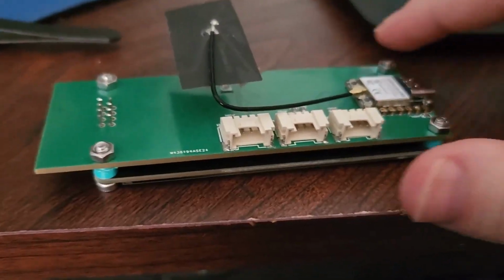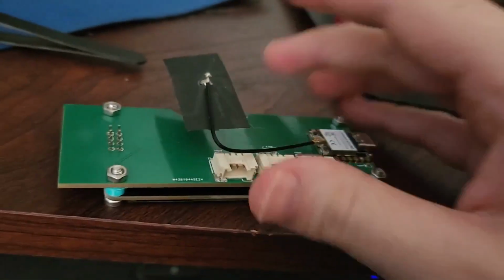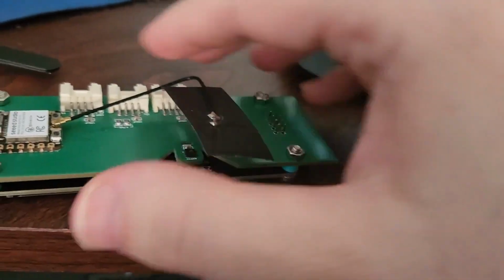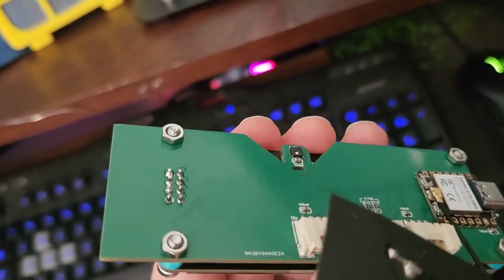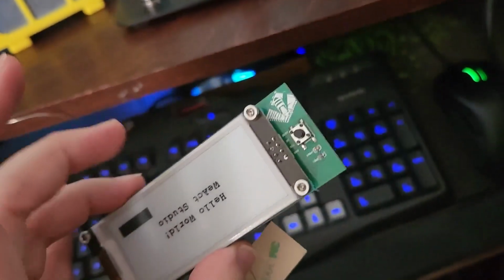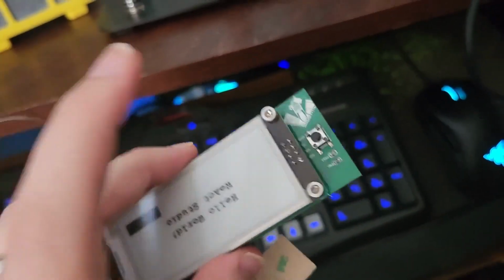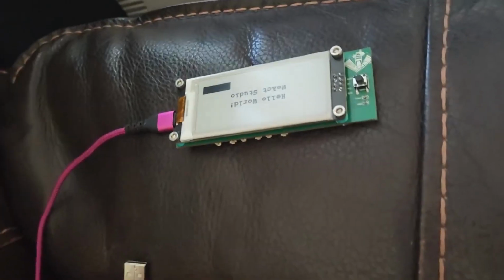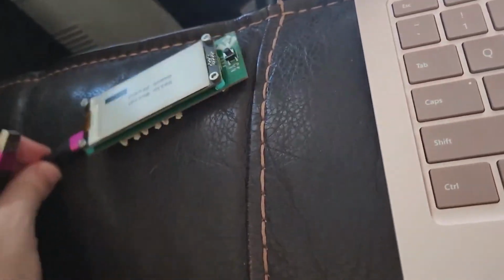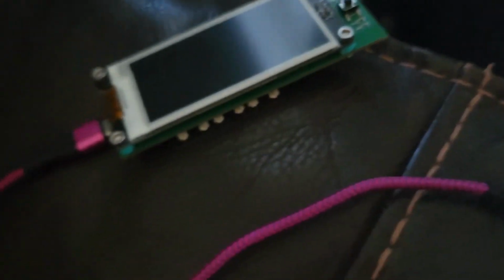I attach these temporary nuts for the standoffs here, just to keep it in place while I solder, and I'm going to use my soldering iron versus the hot air for the remainder of this, just soldering these 8 pins. Angular cutters to cut off the rest of the leads, but it's soldered on there. So now it's just a matter of turning it on and making sure it works. And then I have to add some logic for the button, the temperature sensor and whatnot. But I'm excited. If all goes well, my demo code should appear here, a demo message from me that I'll need to update once I have the code for the entire board ready. Let's give it a shot.